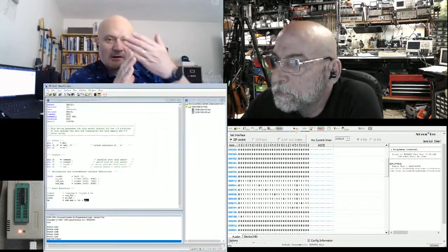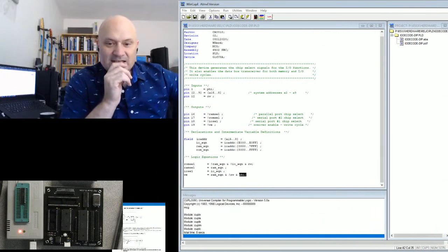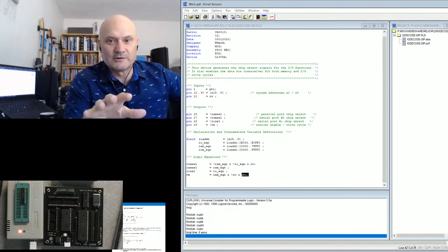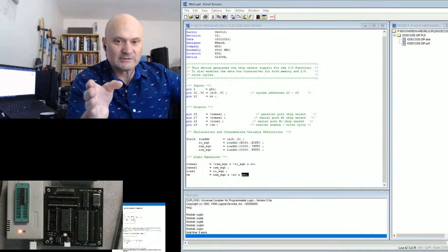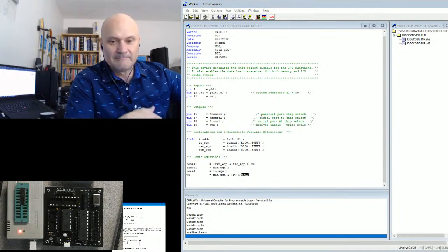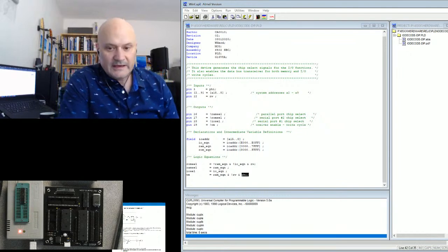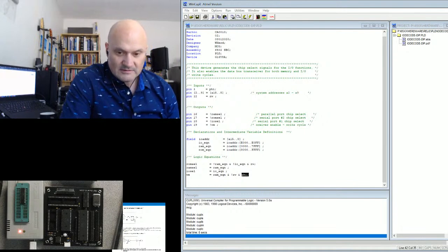So that means the clock may be asynchronous to the write signal. So how do you deal with that timing? Because this is totally cool in a PLD for basic address decoding, and as you said, you don't want the write enable to happen right at some point. There's a tight timing condition in here that the PLD is uniquely qualified to address, and that is the data on a 6502 is only held for 10 nanoseconds. That's 1 LS delay. Wow.